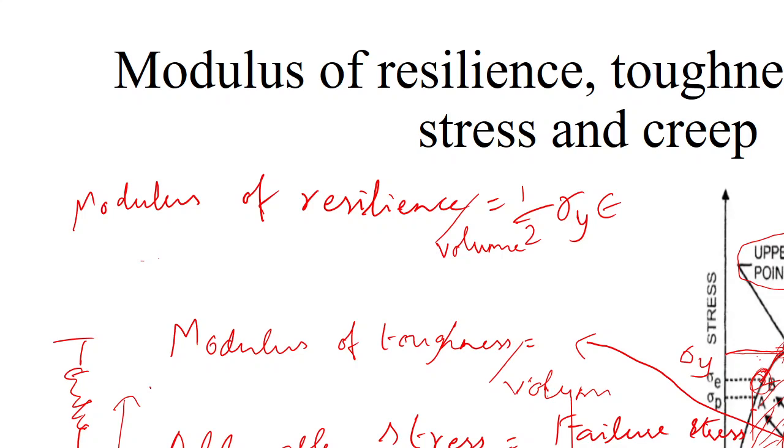So, sir, if we are increasing the factor of safety, that means the cost will increase. See, one point we can say is that since the allowable stress is very low when we increase the factor of safety, we have to support the load with more material.